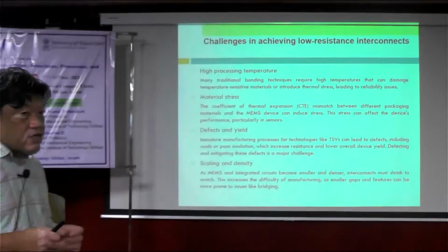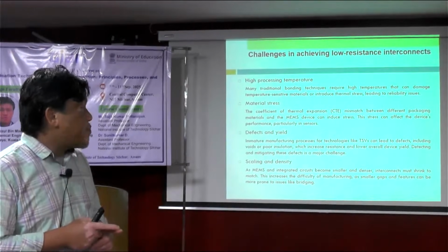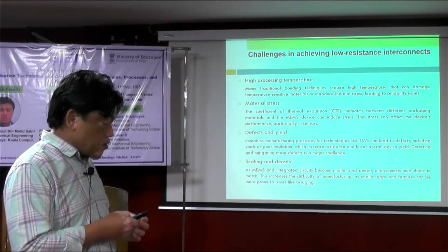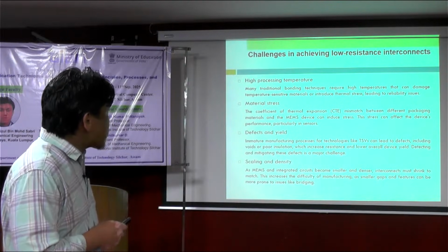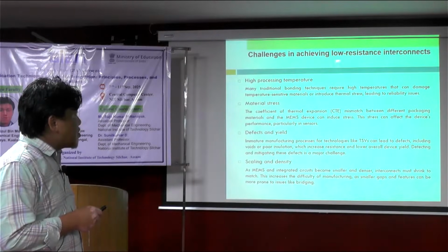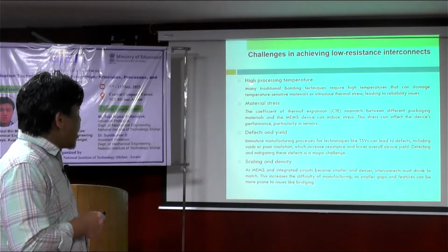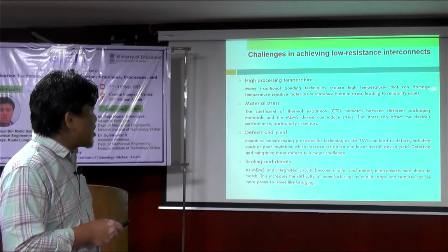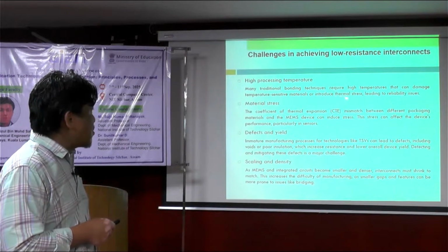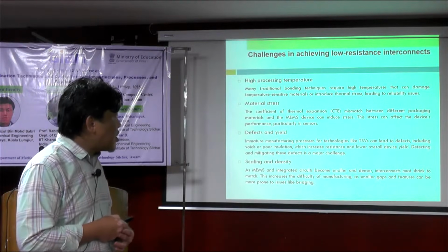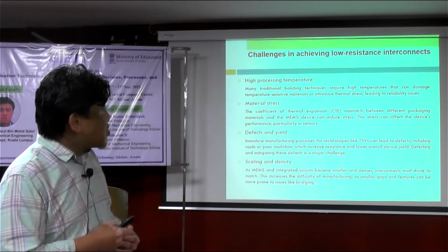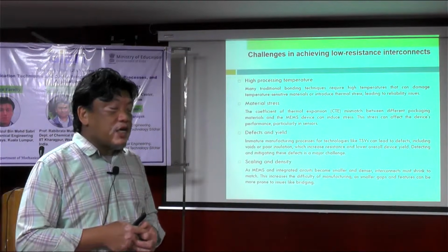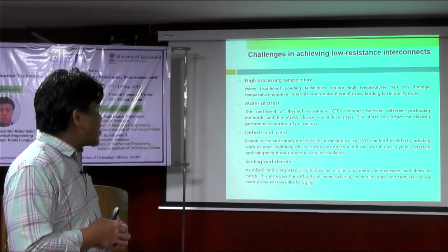And pitch refers to the distance between two solder bumps, for example, and to maintain that manually is also quite challenging. Challenges in achieving low resistance interconnects and high processing temperature. Many traditional bonding techniques require high temperatures that can damage temperature sensitive material or introduce thermal stress, leading to reliability issues. So certain components might deform, might get damaged due to high temperature.